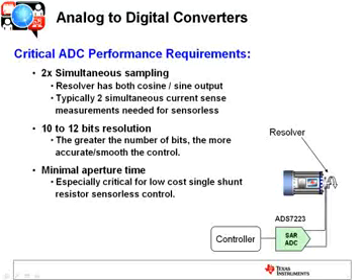When you look at the current sense resistors, it's typically 2, sometimes 3, sometimes 1, but many times it's 2 current sense resistors. So you've got to measure those currents in those legs simultaneously, both the two legs at exactly the same time in order to commutate correctly.